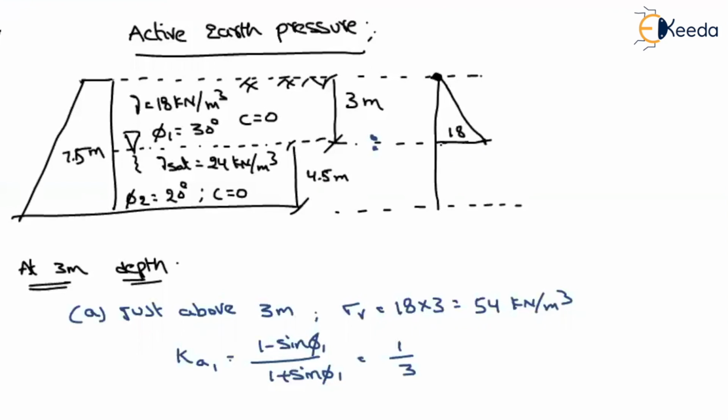26.5. So just below it, I am drawing just below it, but it looks like I am drawing it on the same line, right? But if you zoom in, then only you will see that there is a very small distance between them. Now, in between, if you keep on moving below the surface, again your vertical stress will increase. That means your active earth pressure will also increase.